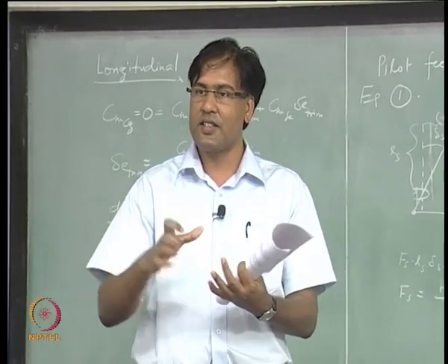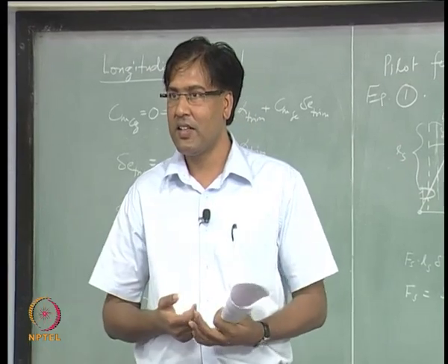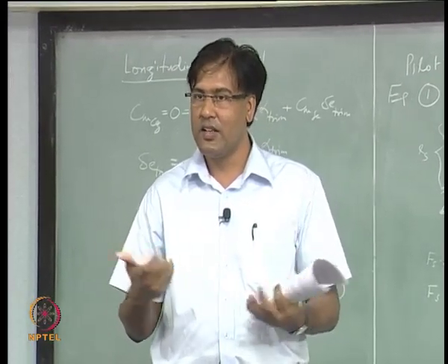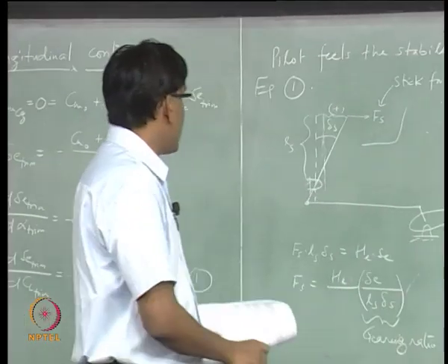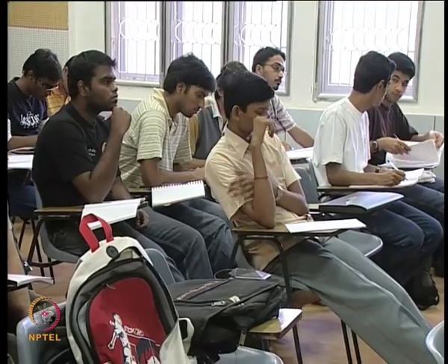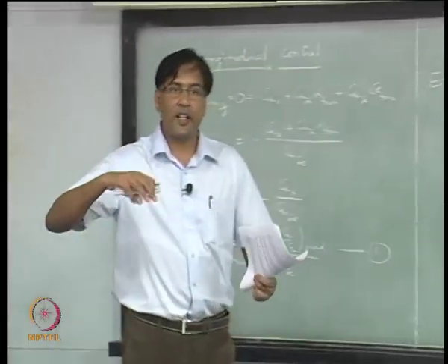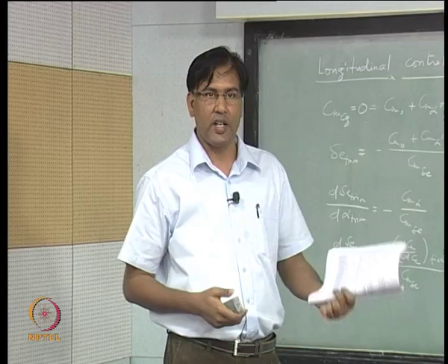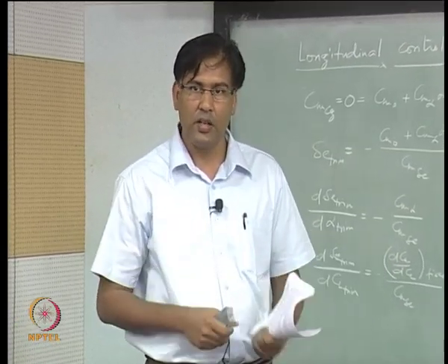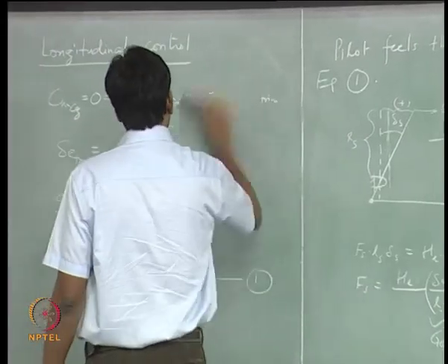If a surface is allowed to rotate freely, what should happen to the hinge moment? 0, right. So, let us look at what happens in such a case when the elevator is not fixed, but is free to rotate, right. You are not holding the elevator somehow. No?